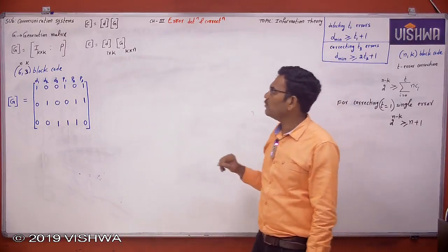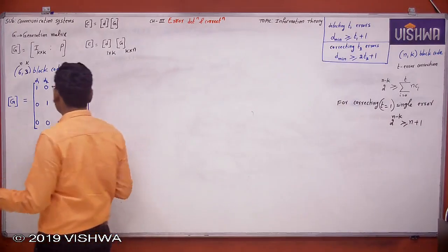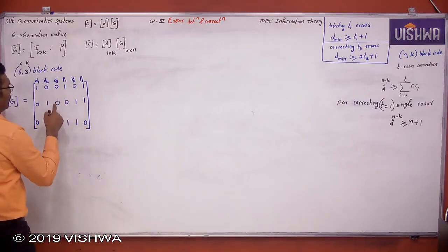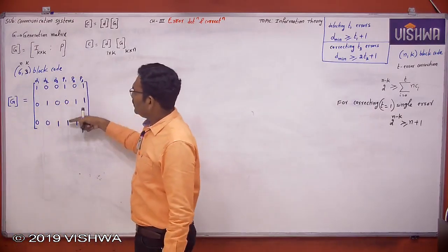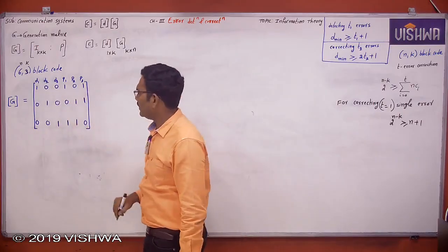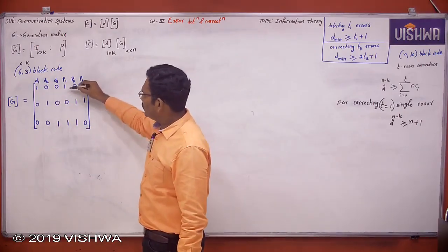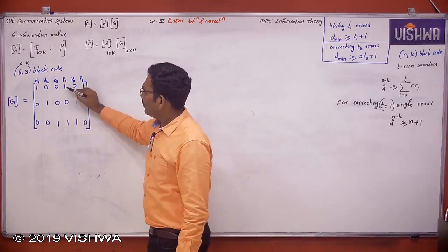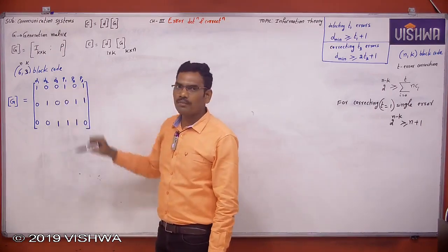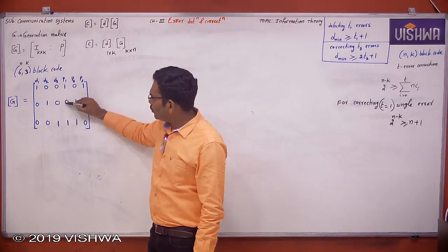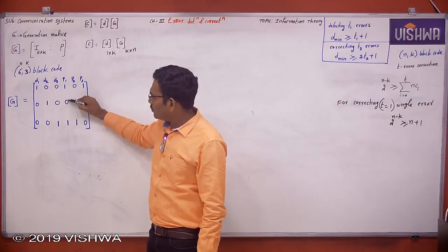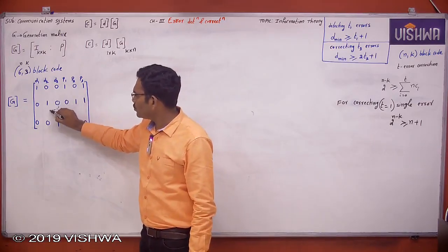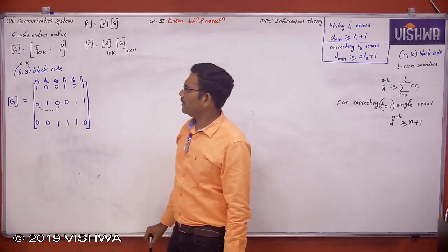First you will try to find the parity equations. What are the parity equations? Now see here, this is parity one, which is a combination of these data bits. Where there is a 0, you can easily identify, and the combination is an exclusive OR operation. P1 is 0 here, so if you want a 0, then you have to do the exclusive OR of 0 exclusive OR 0.